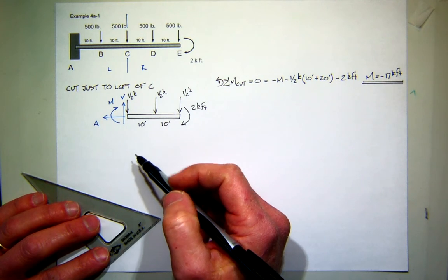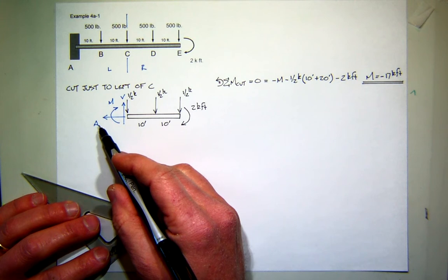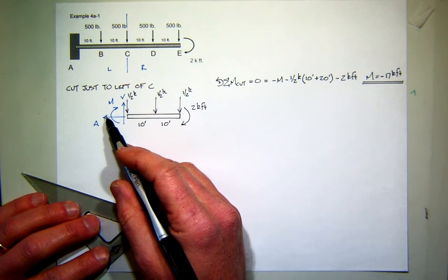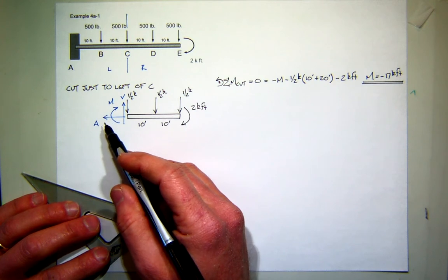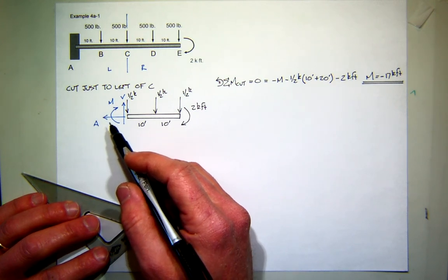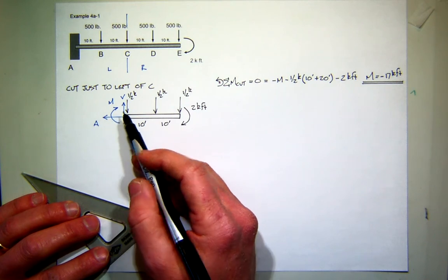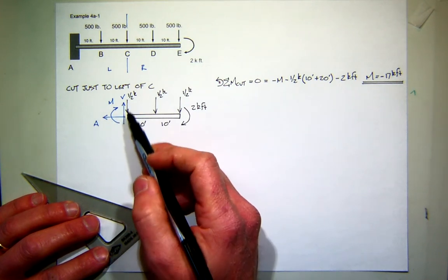What was the axial force? Why did you choose those? That's tension, right? So you always assume tension. I always assume positive sign convention when I make my cut. So that would be tension. And this shear force is positive shear force on that edge.